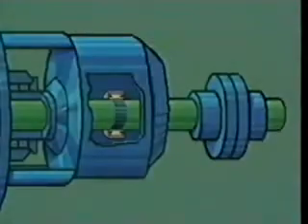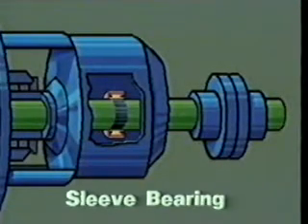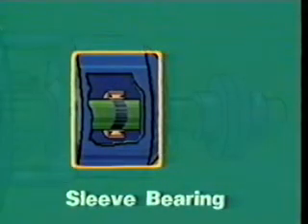The sleeve type is stationary. It's made of smooth metal cylinders in which the shaft rotates. Sleeve bearings are lubricated and cooled by a thin film of oil between the bearing surface and the shaft. That oil is brought to the sleeve by a ring oiler, or under pressure from a lube oil pump.